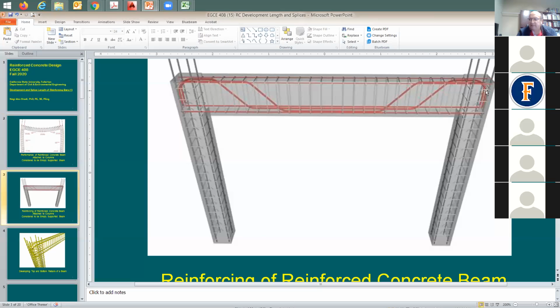Professor, you mentioned that you hook it down. Would you be able to hook the vertical column to go 90 degrees to the left? Beam left? Yeah, so for example, that right column that's going up, would you be able to hook it left instead? You want to hook it where? This side? Yes. If you have another beam, you may, but you would maybe like to put it down here within the column itself. It's going to be much easier for the rebar detailing and for the installation. Got it. Thank you. Yeah, no problem.